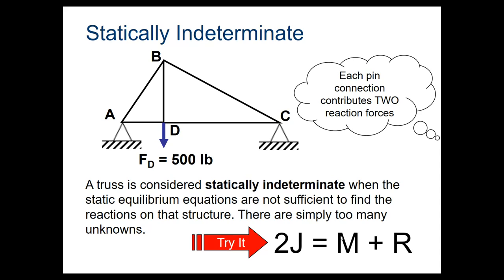And then we start thinking about, okay, well, what about our reaction forces? And so we got to look at our picture. And again, picture-wise, this triangle shape, that represents a pin joint. So right now we've got a pin joint at both ends. And we said a pin joint is 2 reaction forces because it's an X and Y horizontal and a vertical translational force. And so we've got 1, 2, 3, 4 reaction forces here. And so we get 5 plus 4 is 9. And this equation then doesn't work. We get 2 times 4, which does not equal 5 plus 4.